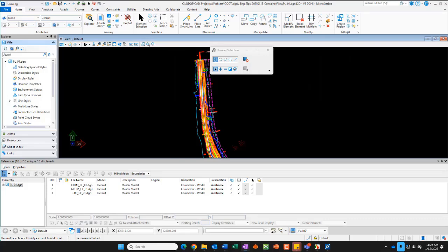This is the reason why I don't recommend leaving the published terrain attached to the corridor or the geometry, because it will make other attachments to the terrain not editable, and it's frustrating. Let me set this up to show you what it looks like to have what are called redundant references and how frustrating it could be to try to change the level display.